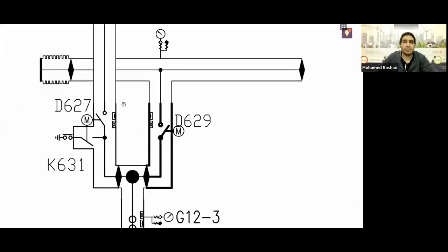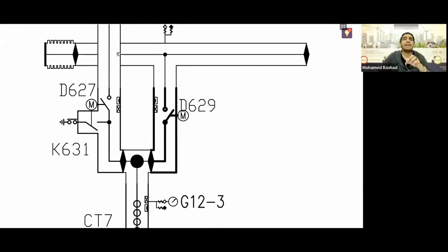The purpose of this ruptured disc is to manage the pressure of the SF6 gas inside, which has a specific pressure limit. The increase in this pressure is allowed up to a certain point. If the pressure exceeds this limit, to prevent the GIS body itself from exploding or breaking, this point comes into play. This point is weaker than the body itself.